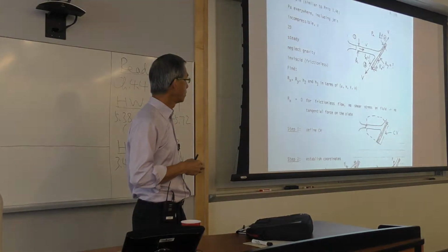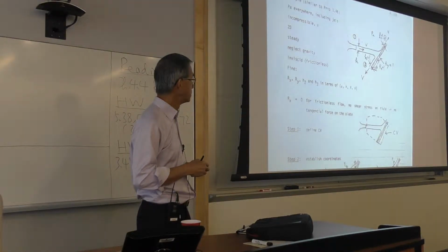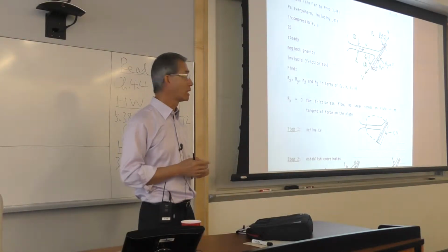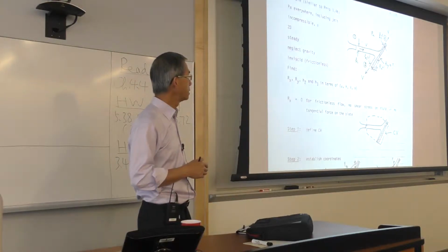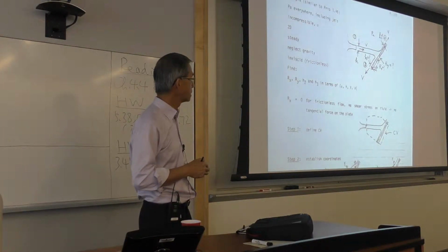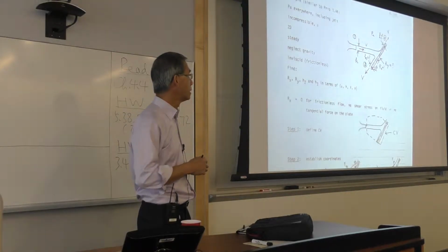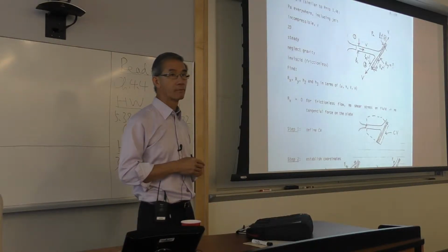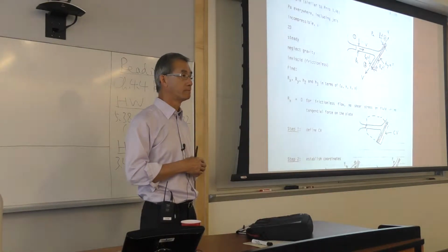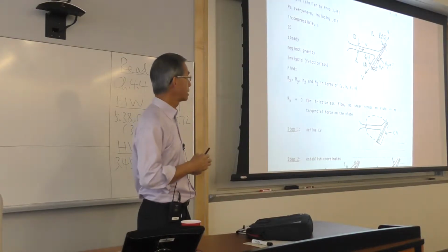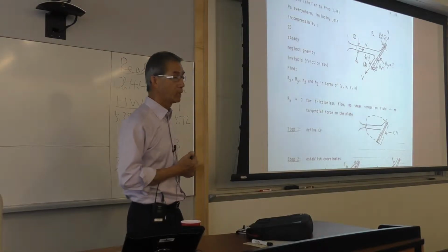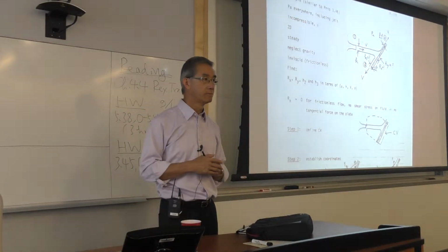There are four unknowns you're asked to look for. As the jet hits the plate, one stream goes up, another stream goes down. You're asked to find the heights h2 and h3 of that split stream. And in addition, you're asked to find the reaction forces Rx and Ry, or in terms of nomenclature, the height of the jet coming out at nozzle 1, velocity, density, and the angle theta of the plate. That's the problem statement.